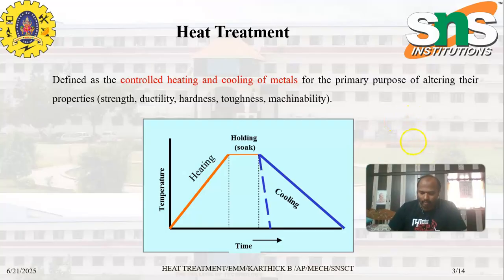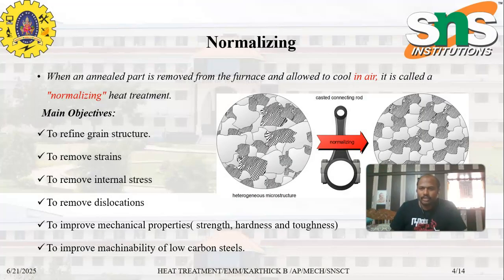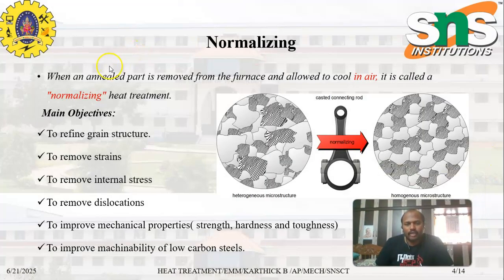But in normalizing, the heated part is removed from the furnace. Here the cooling happens in normal still air. So the particular specimen or piece which is heated has its third step, the cooling, take place in normal air. So it is known as normalizing.